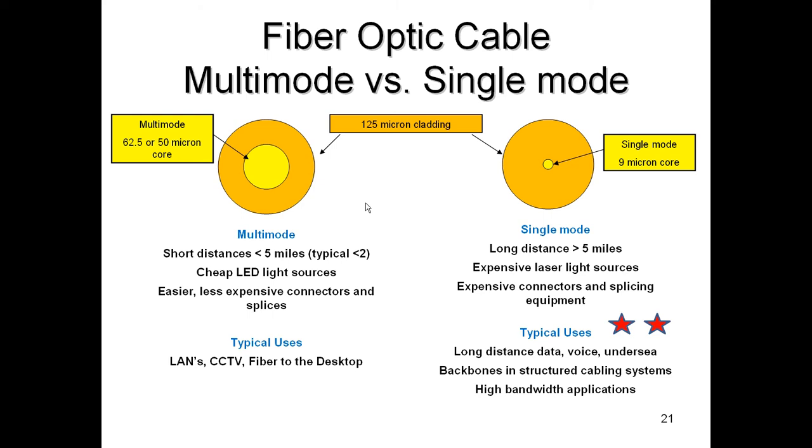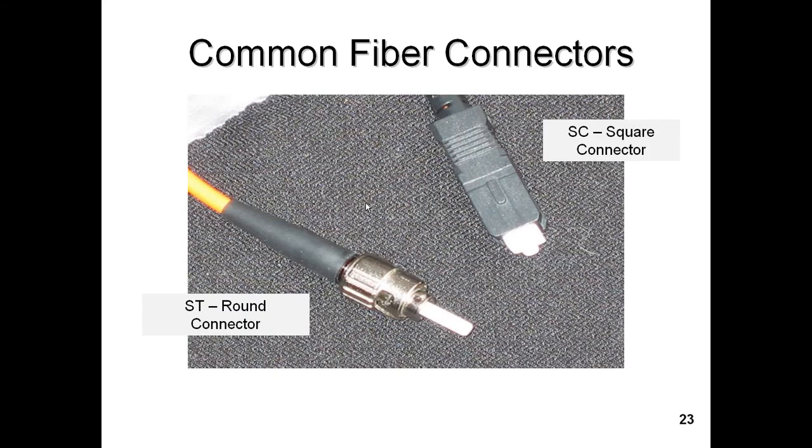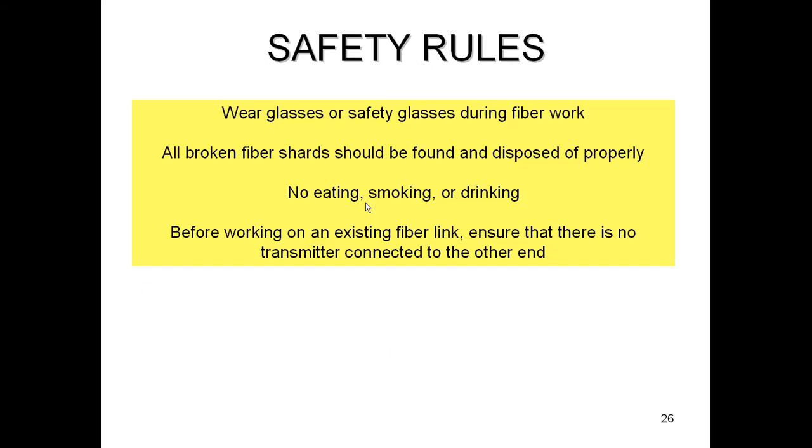So in a functioning fiber optic link, there's light going through it, but you can't see that light. Now, if it's an LED, we can stare at LEDs all day long. That's not a problem. But if it's a laser, the lasers used in fiber optics can be, and often are, eye-dangerous lasers, not eye-safe lasers.